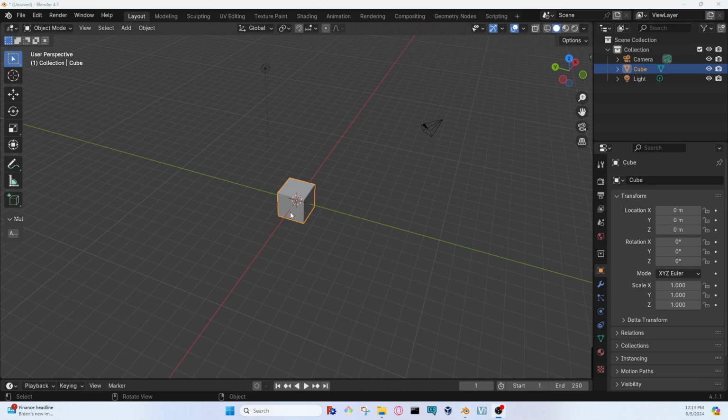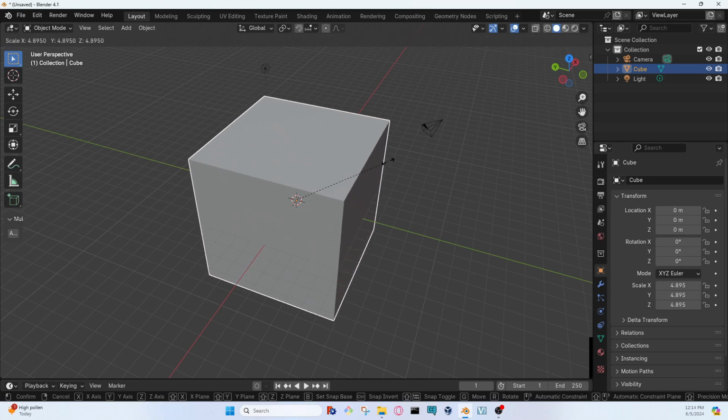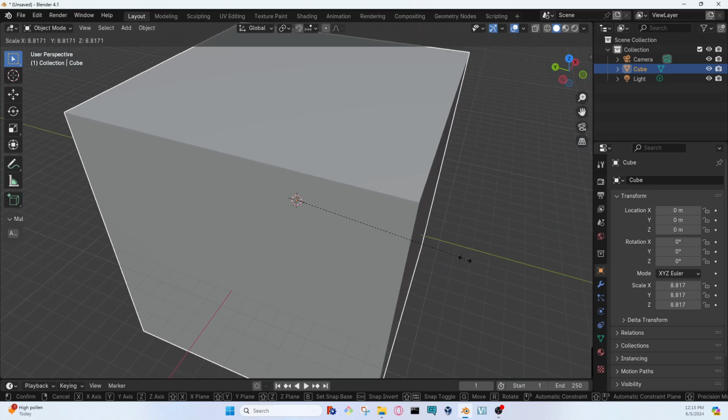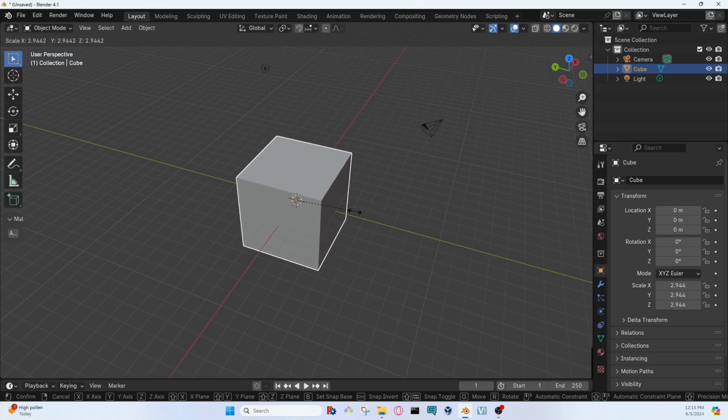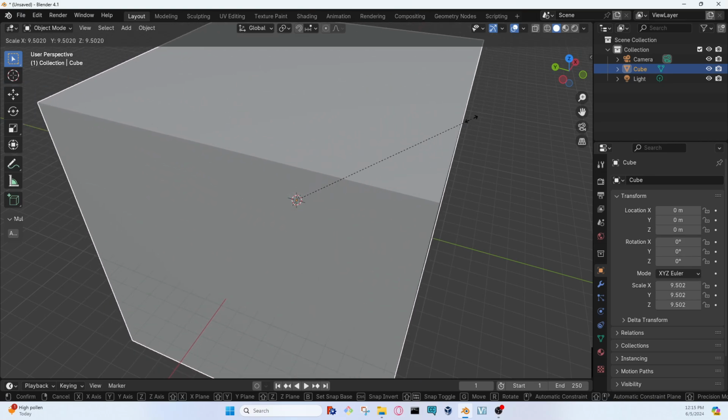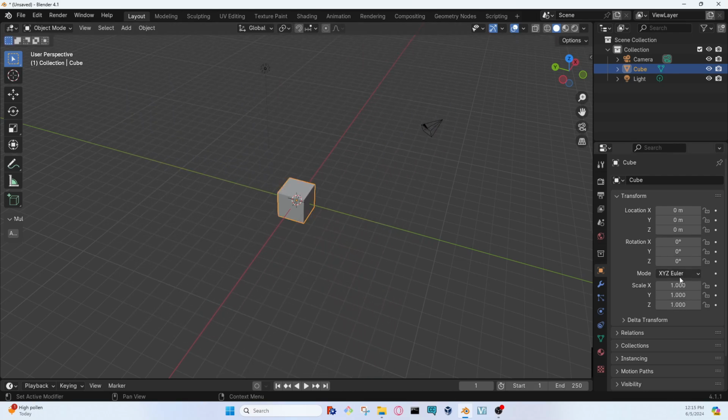Just to go back over everything real quick, grab an object, click on it, G, rotate is R, and now, I'm just going to Control Z that. Now we're going to introduce scaling, which is S. So this is how you make things larger, and you can see in the corner over here on the object data that the scale is going much higher. So it's not 0 to 1, it is an infinitesimally high number. Whatever the base scale was, which was 2 meters by 2 meters by 2 meters, will be 1.